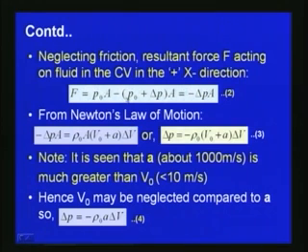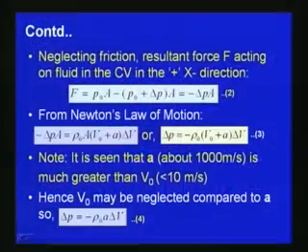So, we consider the control volume between two sections. If one section has pressure P0 and area A, and the other section, with respect to the valve closure and the change in velocity, has P0 plus delta P, then the change in resultant force will be P0 into A minus (P0 plus delta P) into A, that is equal to minus delta P into A, as in equation number 2.